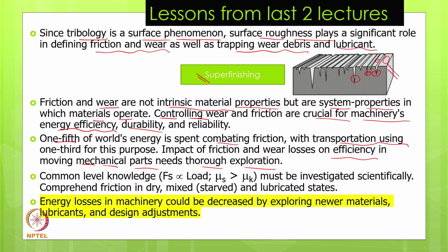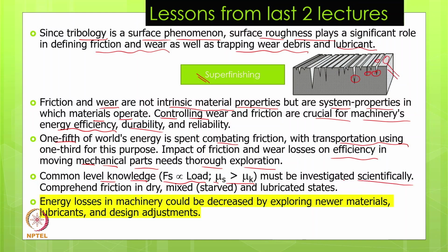There is also what we have already covered, or maybe say learned, about surface friction. There is some common knowledge available. Generally it is said that the friction force is proportional to load. We need to figure out whether this really happens or not. Another thing, it is often said that in a static case the coefficient of friction will always be higher than the kinetic coefficient of friction. It may be, or may not be. However, this needs to be investigated scientifically. That's an important aspect.